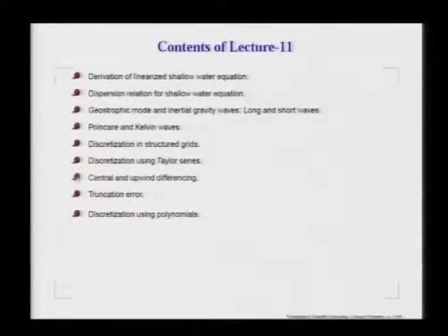We will introduce various types of differencing or discretization. Some discretizations are central in nature, so the discretized equations have some symmetry, or if they are asymmetric, we will call those upwind differencing.